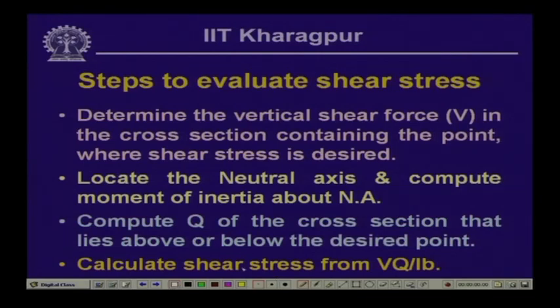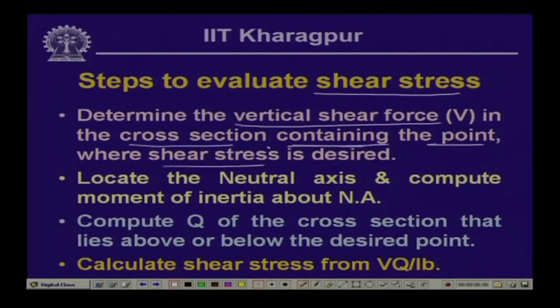Now, to evaluate the shear stress at a point in a beam, first of all we need to find out the vertical shear force V in the cross section where we are trying to find the particular shear stress. That means, at the point where we are evaluating the shear stress, we will have to find out which section that point is in, and at that section we will have to calculate the value of the shear force, and this we can carry out by drawing the shear force diagram.